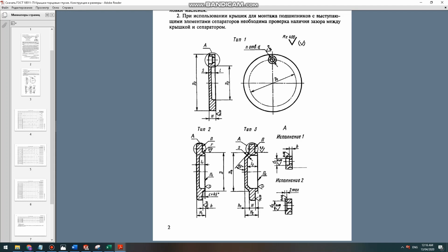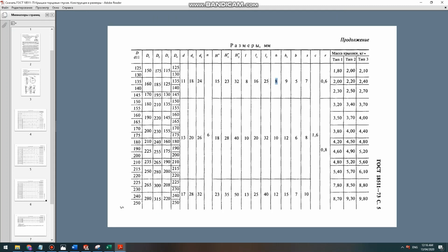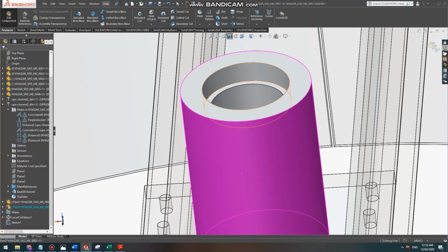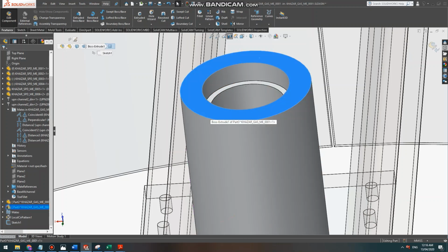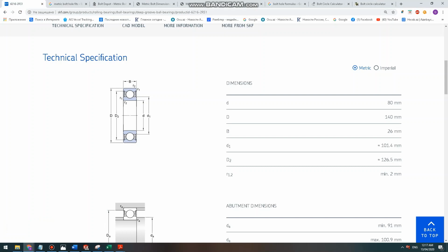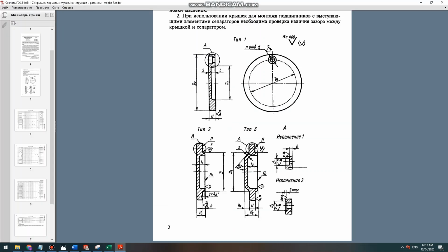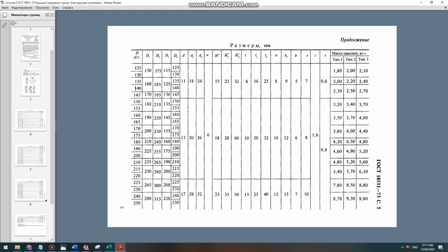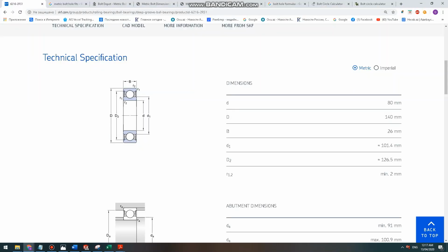Okay, let's look at it. So all dimensions are here. You just take these dimensions from this line 140 and insert them there. That's all you have to do. You have to be careful, and that way you draw the cap, you draw the bolt circle, the number of holes here. It also gives N, the number of holes, and D is the hole diameter. So if you go to 140, you go for N, it's 6, so there must be 6 holes, and D is the hole diameter, so it's 11 millimeters, which M10 will be used.